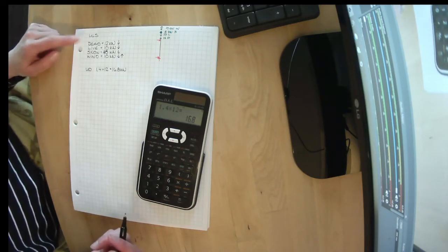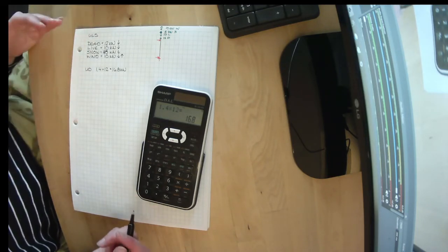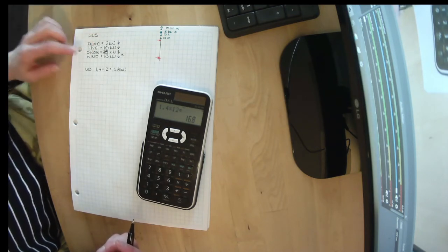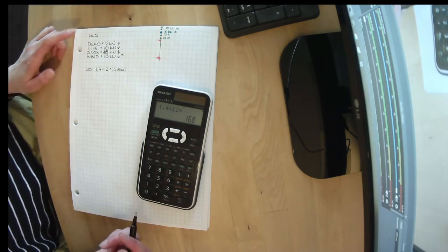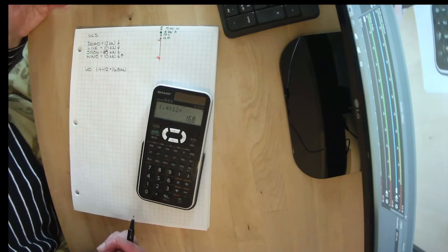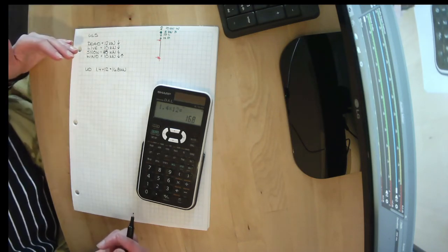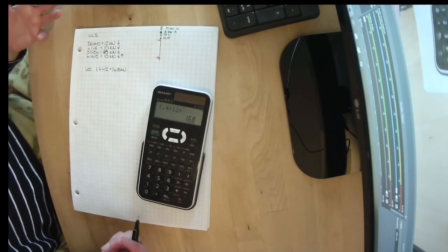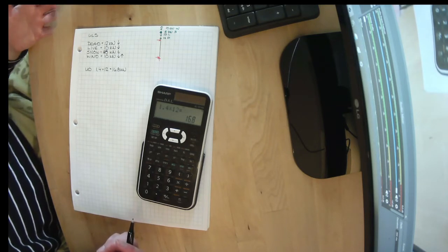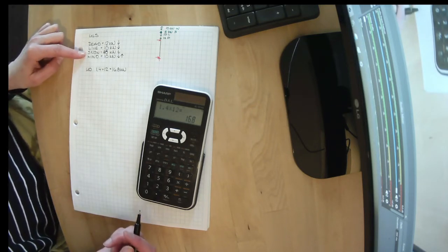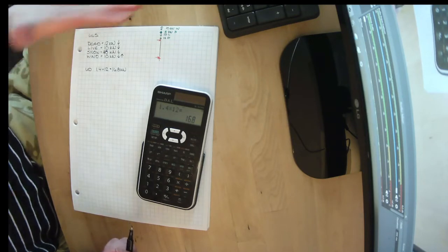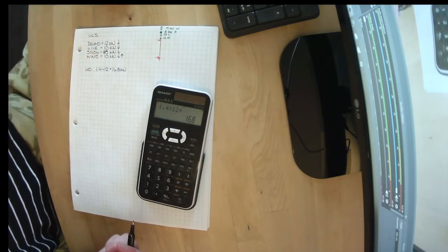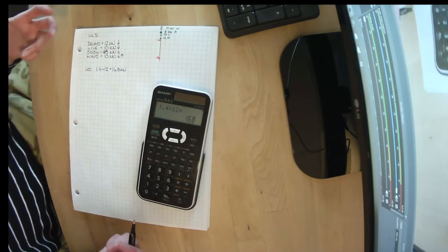Remember, dead load we know comes from whatever makes up the building and the tributary area. We know live load comes from an assigned value in the code and its tributary area. But it might not all always have that live load on it at the same time. We know snow comes from climatic data, and it covers an area of the roof or a canopy, but it might not be there.